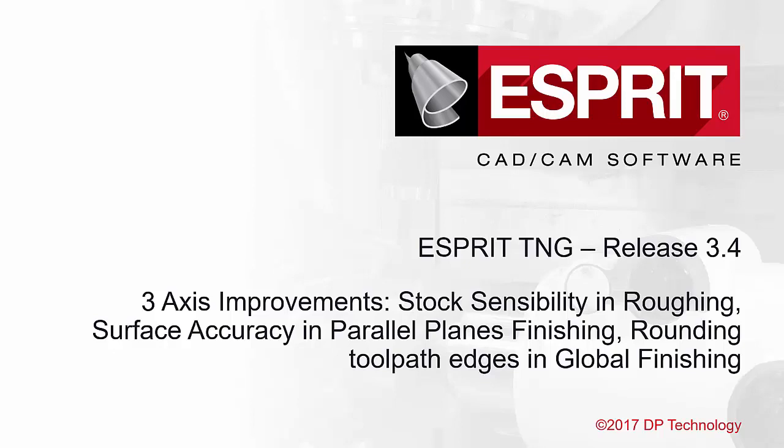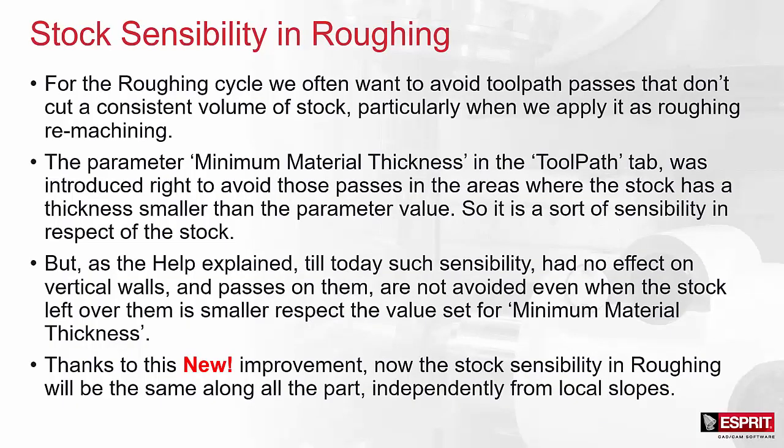We will show today three important improvements in the 3-axis: stock sensibility in roughing, surface accuracy in parallel plane finishing, rounding toolpath edge in global finishing. So, stock sensibility in roughing.